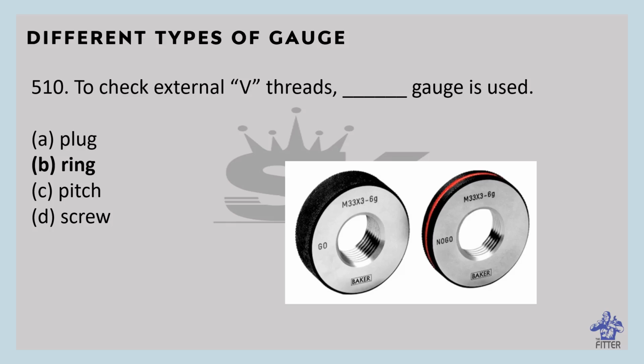Ring gauges are used as comparative gauges as well as for checking, calibrating, or setting other gauges of other standards. Ring gauges are metrology tools that are used for gauging the outer diameters of pins, shafts, splines, fasteners, dowels, and studs.